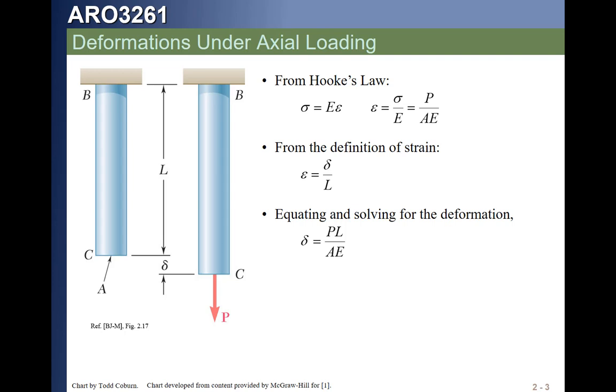So far, we've learned a few key terms. The stress for an axial force, the average stress, is P over A. You should have that memorized. I'm not a huge fan of memorization for engineering classes, but there are certain equations that should be memorized. For example, there are many things that you don't choose to memorize, many pieces of news, but you probably know when your birthday is and what your name is. This is like one of those basic concepts: P over A for stress. For deflection under axial load, PL over AE. Okay? This is some of the things you're going to need.